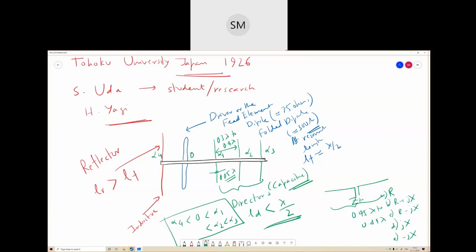In some Yagi-Uda antennas, the subsequent directors are even smaller in size. Okay. In some, it is not. Can we write this? That as we move on from the reflector to the feed element or the driven element to the directors, there is a gradual change of phase, and the currents in each element are leading the previous elements in phase. Is it okay?